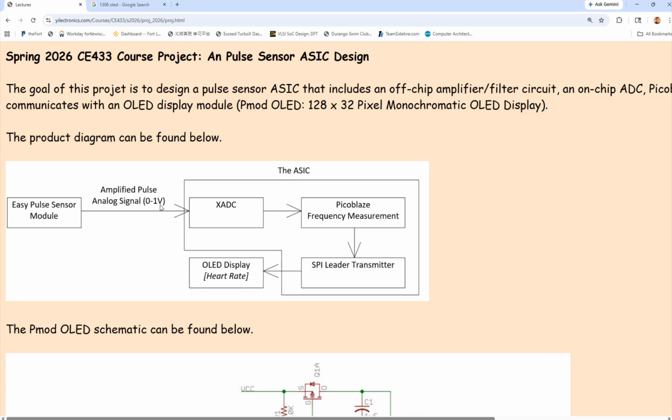But if you are able to do it, it's comparing 3 values, right? The previous value is smaller than the current value, and the next one is also smaller than the current one. Then we know that it's a peak. Then we record the time, but we have to use the interrupts and all the timers. It's getting very complicated.